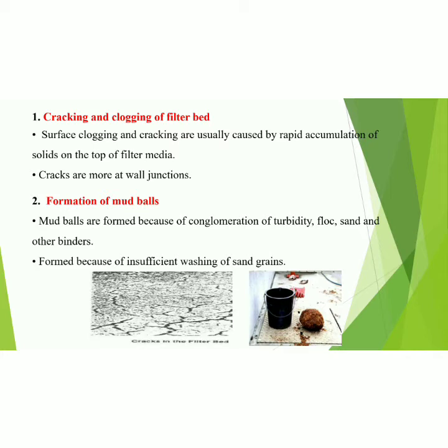So cracking and clogging of filter bed takes place, and formation of mud balls, that is, mud balls are formed because of a conglomeration of turbidity, flock, and sand and other binders, formed because of insufficient washing of the sand grains. So if some impurities are present when you add the sand to the filters, without your knowing, it will also cause some formation of mud balls.